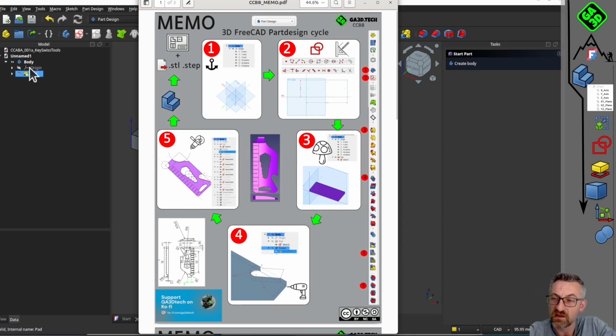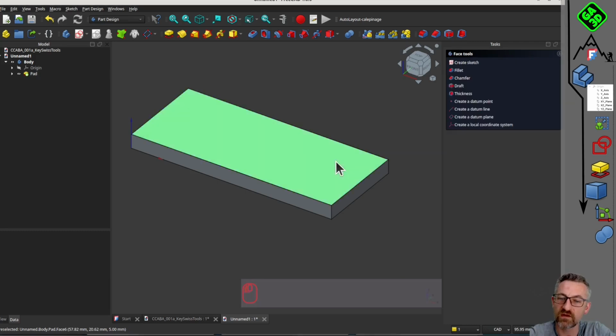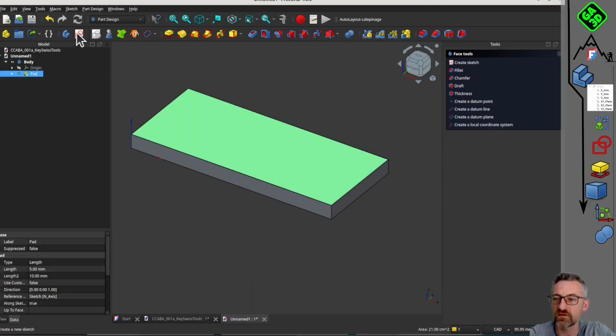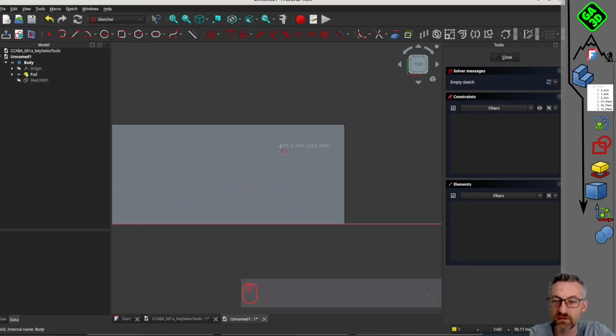Step 4, to do a material removal, we'll follow the same process. We'll define a geometry, so place a sketch, either on the origins of our part, that's ideal. But then we can also position our sketch directly on a face of the volume we just created here. That's what we'll do in this example. And then we'll do an operation from zone 4 here. These red and blue icons. These are material removal operations, so we'll see that right away.